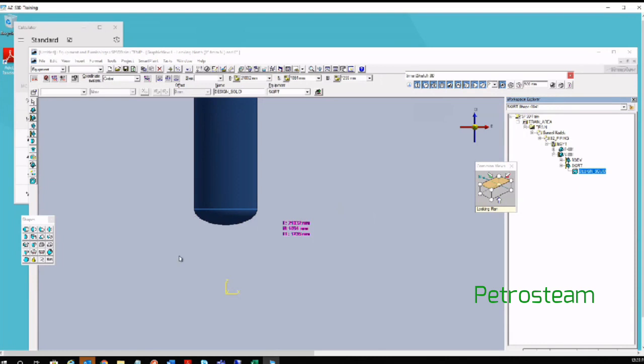For that, you need a conical shape for the skirt. And if you have to make a through hole in it, it should be a positive shape. Any positive and negative shapes, we have to build using positive and negative shapes. There should be a positive shape in which we will add one more shape, which will be negative, to cut the hole. Both of them should be within a design solid so that they will apply as positive and negative shapes.